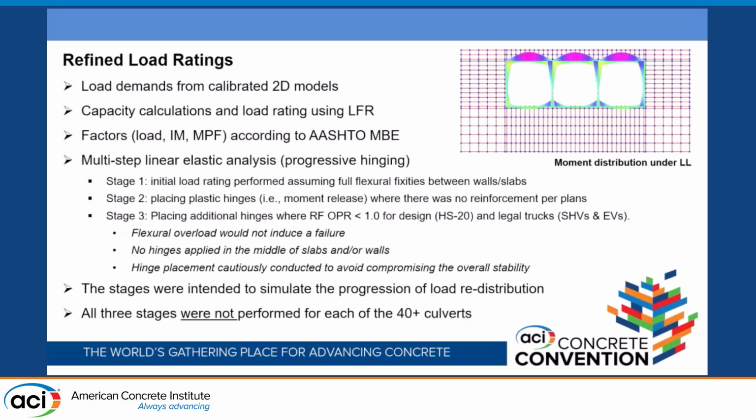So with that, we proceed with the refined load rating analysis of the entire population of the culverts that were assigned to us. All of the 2D models were created. We did the capacity calculation based on the plans, following the AASHTO MBE, using the LFR method.